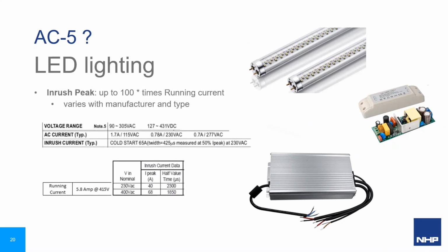LED lighting uses lamp drivers and control boxes to power the LED lamps. These drivers and control boxes are electronic based, so startup and operational current loads should be obtained from the lighting manufacturer. Examples seen of drivers with 66 times for 300 microseconds or inrush of 80 times for 400 microseconds, and control boxes with 12 times for 2 milliseconds have been seen, so ratings vary widely.